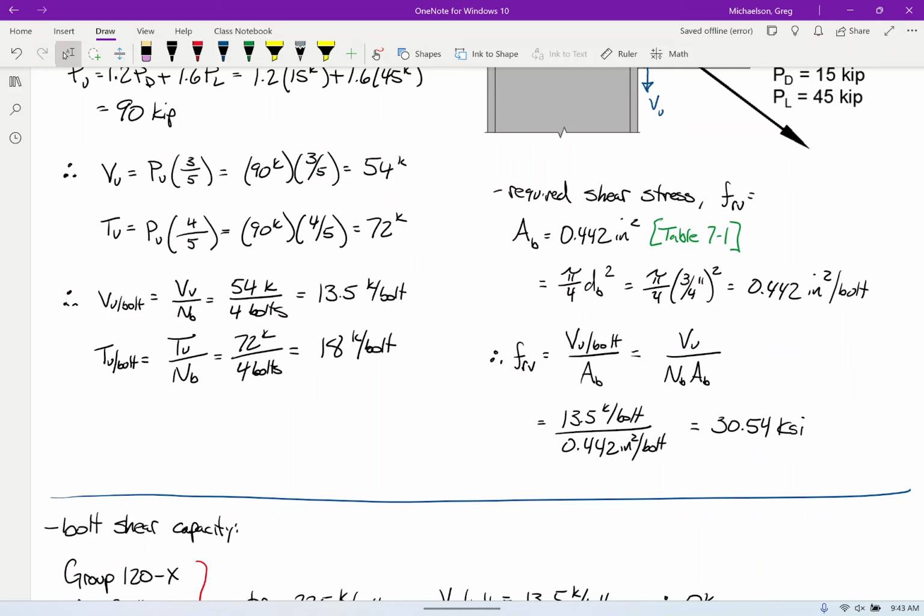What is 30% of 72? It's like 21.6. So as long as this number is bigger than 21.6, that means you need to do interaction. That's what that's saying. So what I'm getting at is we could have looked at the very beginning of the problem and said, yeah, we're going to have to do an interaction check. It's going to be necessary. With me so far?